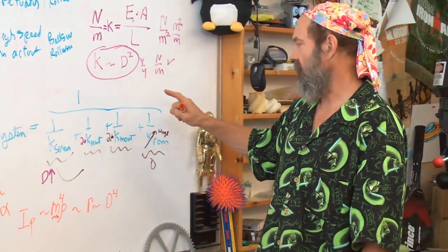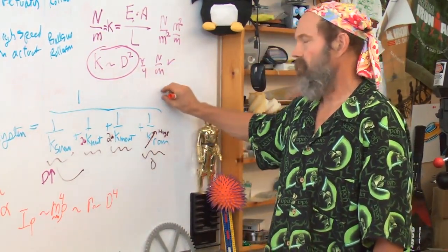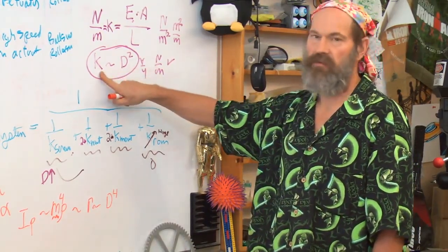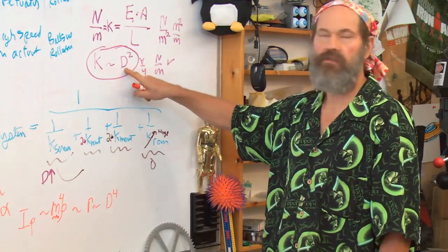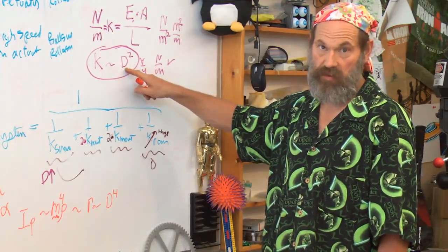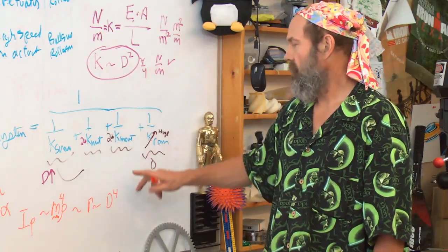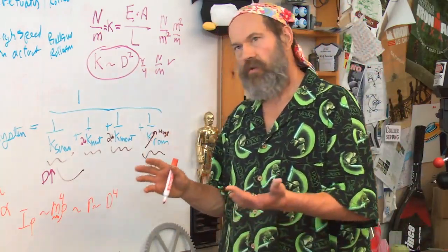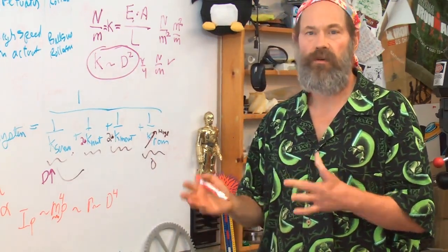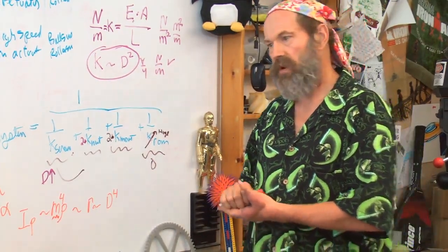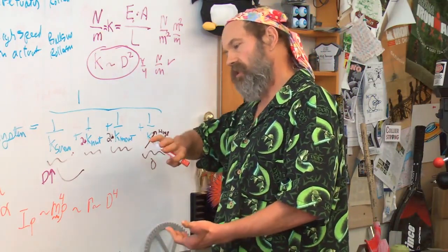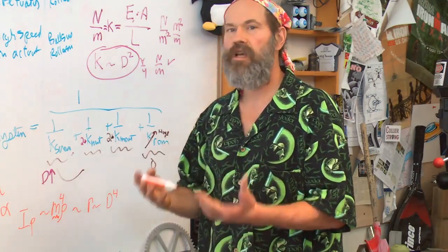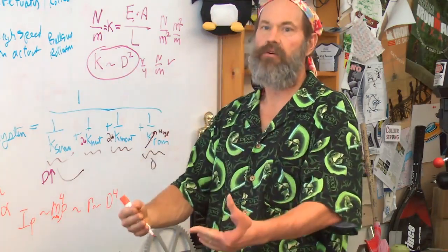And now the challenge you have is that if I make the screw shaft bigger by a factor of, let's say, I want to increase the stiffness by a factor of 2, so I make this 1.4 times bigger, so 1.4 squared is 2, the rotary inertia will go up by a factor of 4. So by making the screw shaft bigger in diameter just so I can get higher stiffness by a factor of 2, it takes me 4 times the torque to accelerate the load.